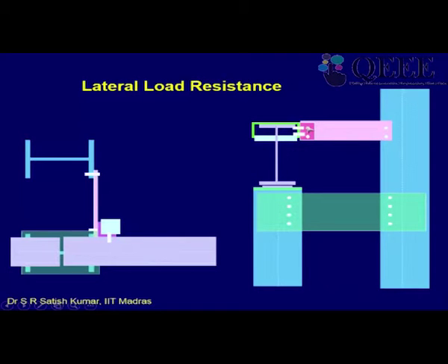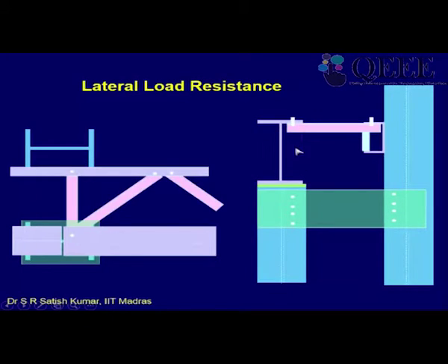So look at this figure. This is my gantry girder, and this is a sort of a stepped column which is battened, right? Typically, when you have a gantry girder, the column is made up of two I sections which are laced or battened together to make a single section, and one of the I sections is terminated, on which the gantry girder is supported, and from the other section which goes to support the roof, some lateral support and torsional support can also be given to this girder. Okay, so that is one way of designing.